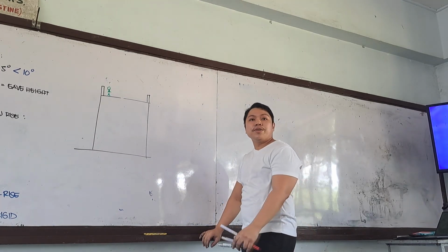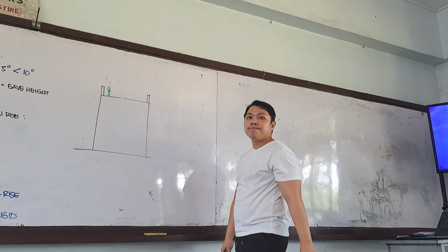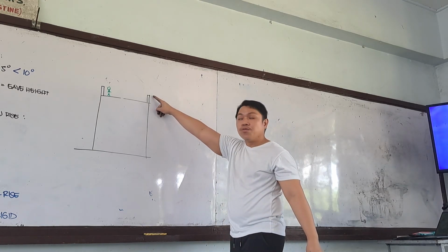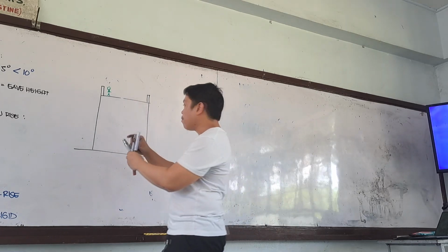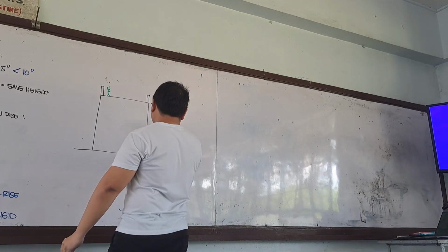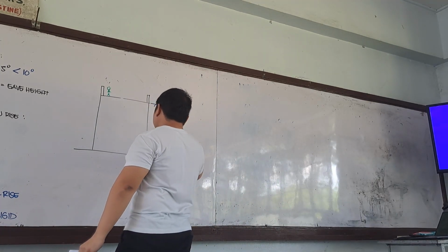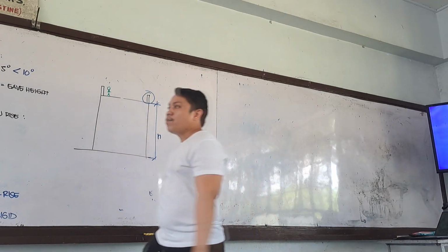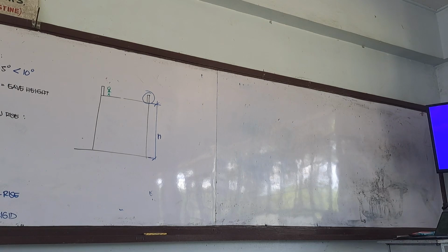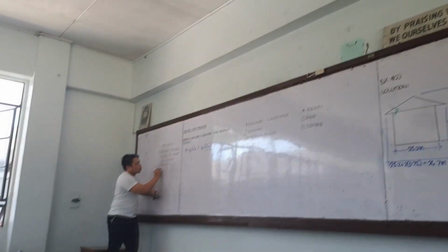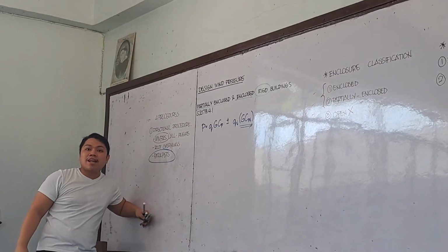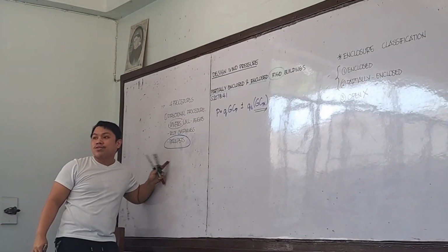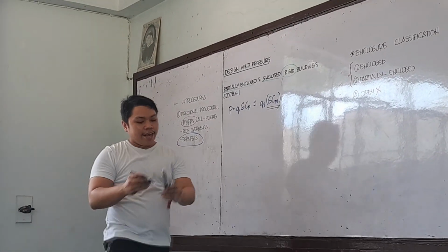What is considered the mean roof height? The wall is not the roof, right? The wall is not considered roof. So this would be our mean roof height. Okay, sir, what is the consideration for our parapet wall? We will use Section 270.4.5. We will have conditions for parapet walls for those occupations. Okay, clear?